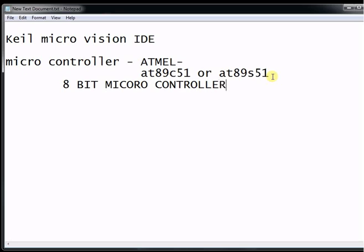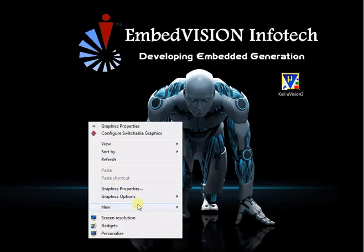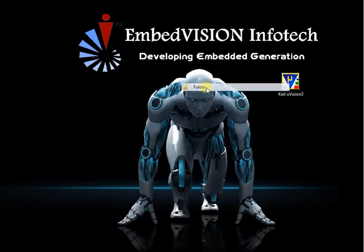So for generating hex file we need this software Keil. Keil software is absolutely free on the Keil website. In this tutorial we will learn how to use it. So first of all we need to generate a folder on the desktop or any place where you want to make your project. Name it anything you want. Project.